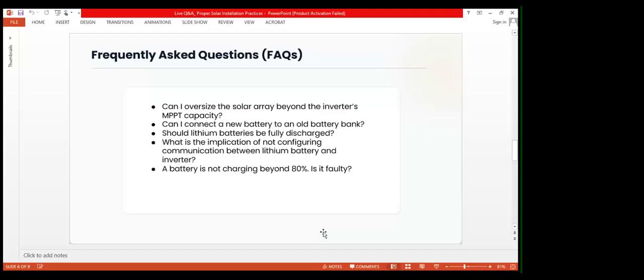That is overcharging in terms of current. It's going to get damaged. So what you can do technically, which is not advisable for a customer, if you're a technical person and you want to do this, you can do it. For customers, we just say don't connect old batteries with new batteries because it's complex. It will take you a longer time and customers will not understand. But if you're a technical person and you want to do it, you can do it and follow.